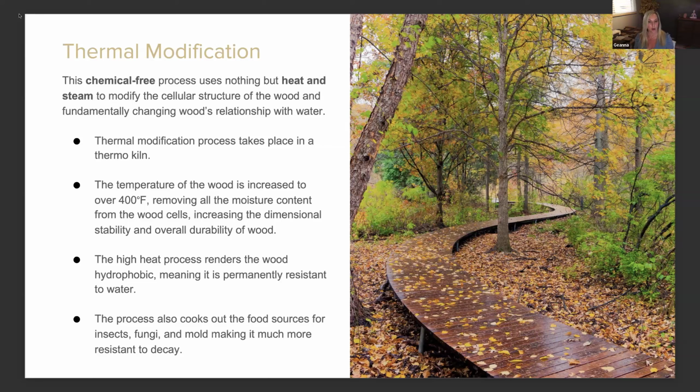The process cooks out all of the sugars, all of the food source. So there's nothing left to rot, mold, mildew. It absorbs so much less moisture. It gets less hot. There's no sugars. There's no food source. So it's termite resistant. For people on the West Coast where termites are a huge issue, thermally modified wood is termite resistant because there's no food source. There's no sugar for the critters to eat. It is not woodpecker resistant. We do get asked that question a lot because woodpeckers are going after the wood fibers as a nesting animal.